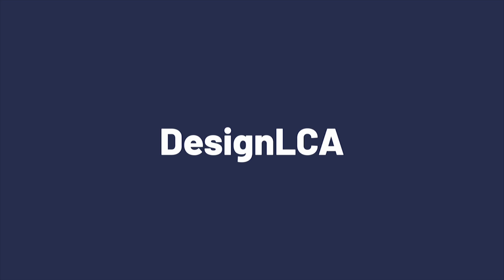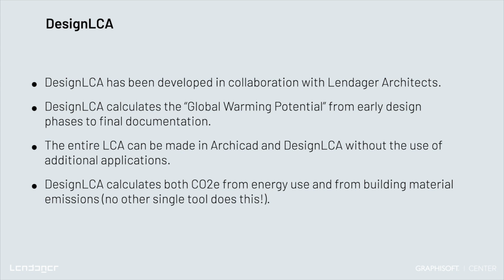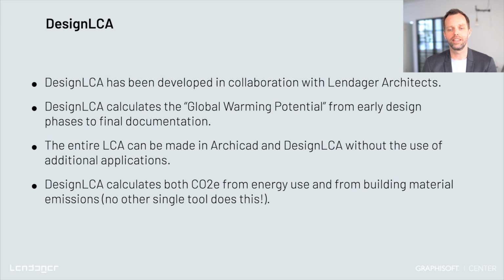This is the plugin we have made for Archicad to do LCA calculations directly in the BIM project. We've done the plugin in collaboration with Linear Architects, and what it does is it calculates the global warming potential from the early phases of a project and all the way through the detailed parts of the project too.